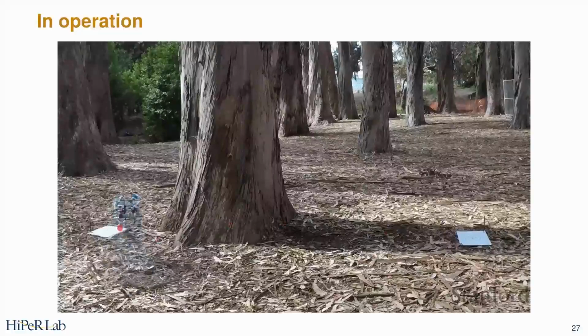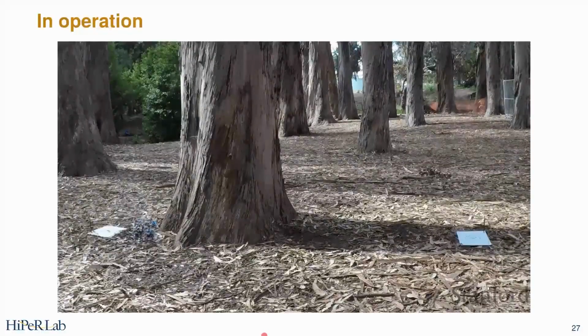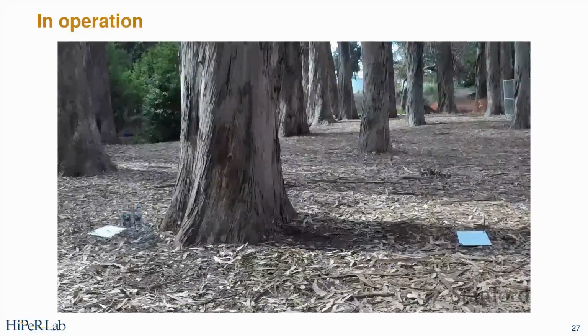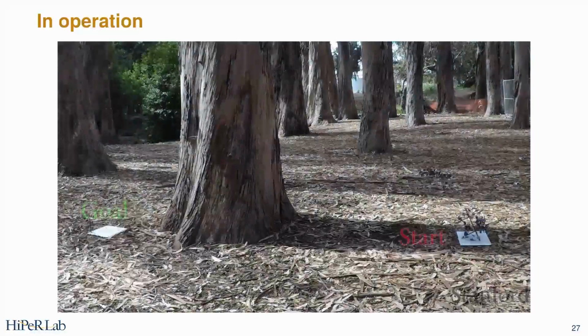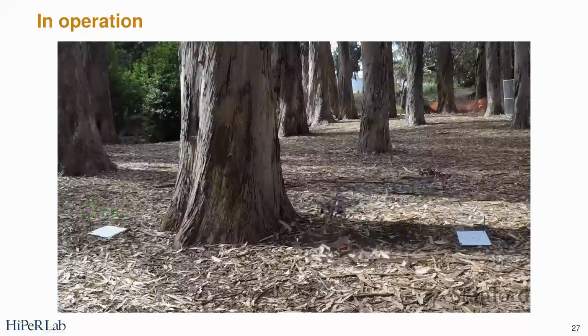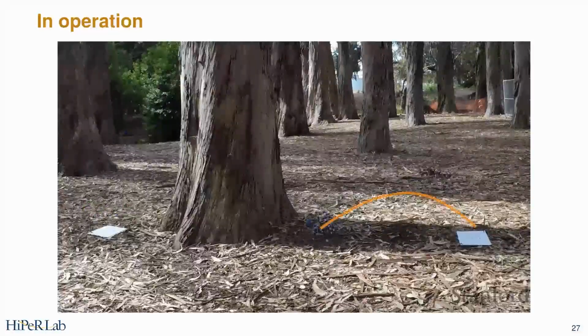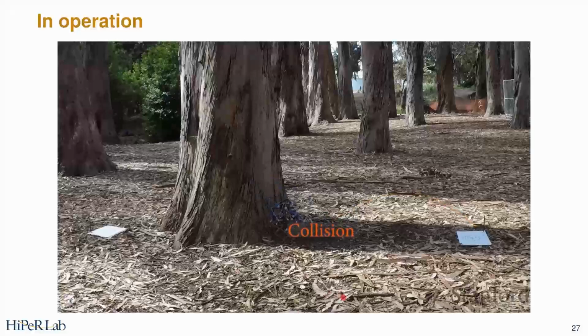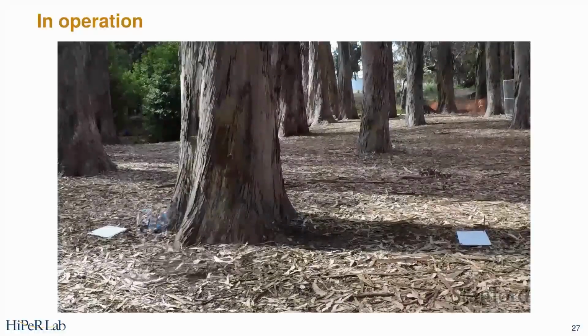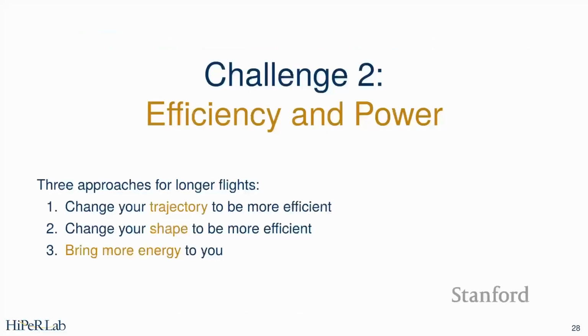But I want to just sort of show here, it's kind of impressive that you can get pretty good dead reckoning from this. And the key here really is the hopping. So this is a zero velocity update. I got this idea from people who were doing foot tracking with IMUs when you do footfall. And the idea is when you know you're stationary, you can do a Kalman update with zero velocity. And this really sort of shrinks that dead reckoning error from t to the 5 to in the order of t. Okay, so that's cheating to solve the problem, I think.